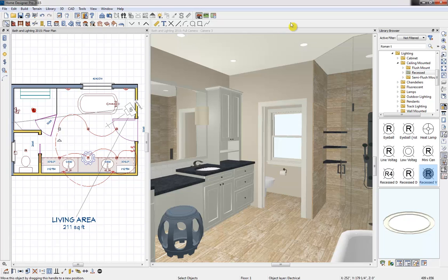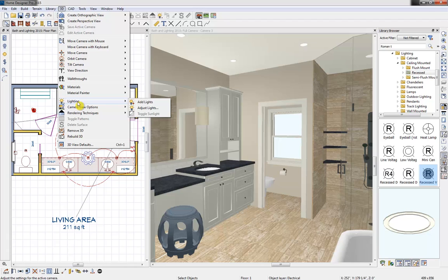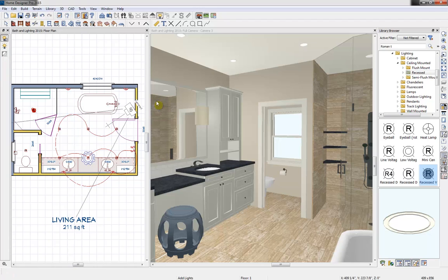And if you want to add additional lighting without actually placing a fixture, this is mainly for rendering purposes. If you need additional light in a specific area, you can get into your 3D, into the lighting area, and we can add lights. So you can see my cursor now is kind of that bright light image. So we can either drop it, or we can click and drag it to parallel or that spotlight or back to the point light. As you can see, if I drop it in, the lighting changes, it's modified, and that works the same as all of the different fixtures as well.